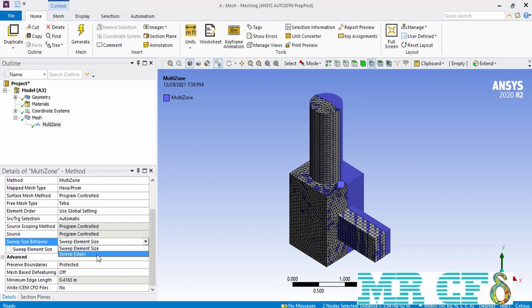After creating the specific type of mesh over the cross section of your smaller box, the direction that you want to sweep your mesh is the depth of the smaller box. Therefore, you have to select the edge placed along the depth of your geometry. It also should be pointed out that the edge that you're selecting should have cell divisions on them. Placing cell divisions over an edge will be explained in next sessions.